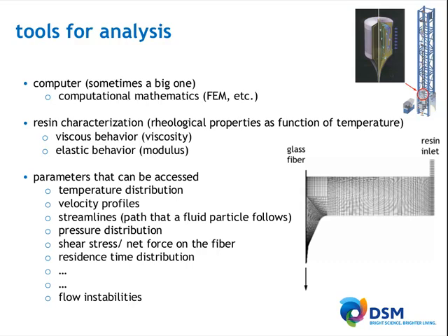Just a little bit about the resin rheology, because now we have a primary and a secondary. And what we typically see is that they have different rheological behavior. The simple way to look at it for me as a non-chemist is simply like this. We have functionally acrylated oligomers. There's a photoinitiator. We start to build a network upon the UV